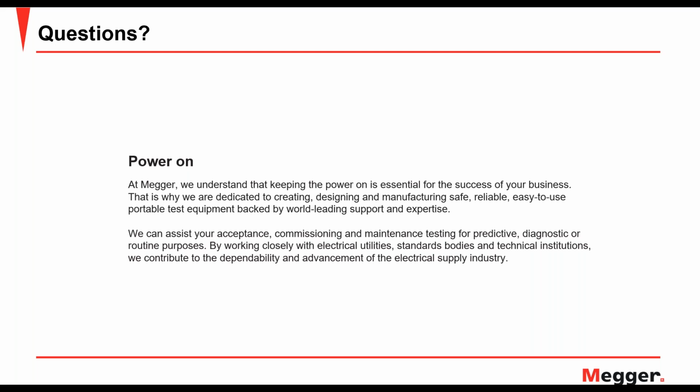Of course, you want to make sure if you have the value of being able to compare to previous, which is gold for analysis of SFRA test results, you should certainly decide, hey, instead of testing at 10 volts peak to peak, I want to match this previous, and you have the ability to change your test voltage to any other one that may match a previous test result.